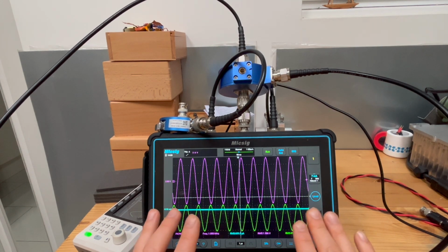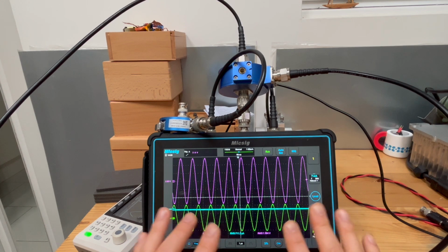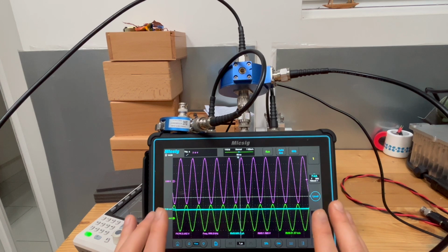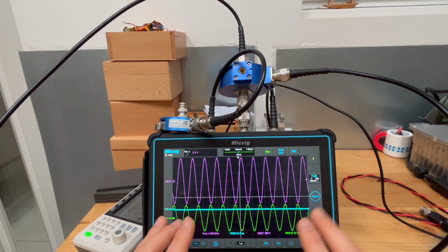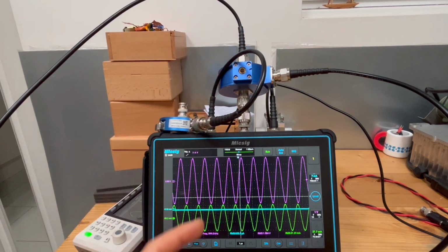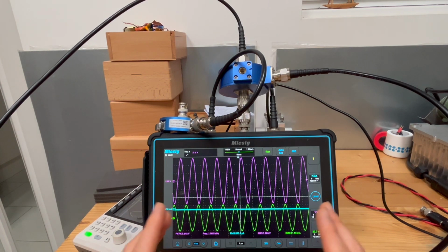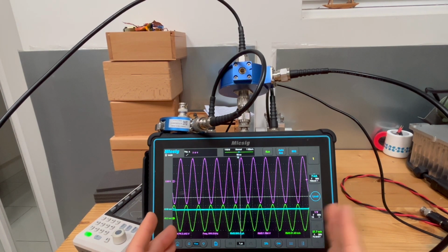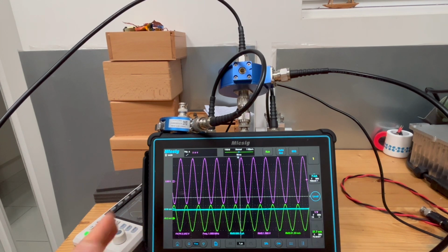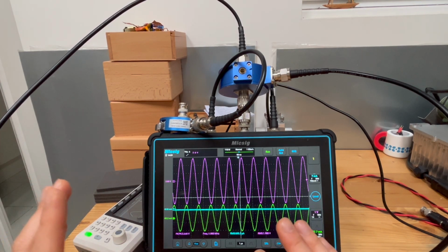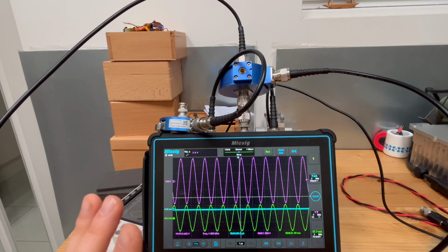All of this is, I'm afraid, not within the scope of this discussion. It's something I know, but it's going to take a lot of time to explain. The reason is the current probe we use. You have a voltage region and a current region, and because of the transfer impedance of this particular probe, when you operate below 1 megahertz, you operate in the so-called voltage region. If you want to know the details about this, you can check our RF current probe series. I'm sure you will learn a lot.